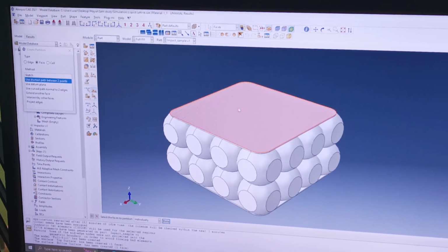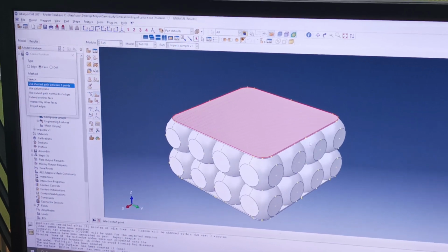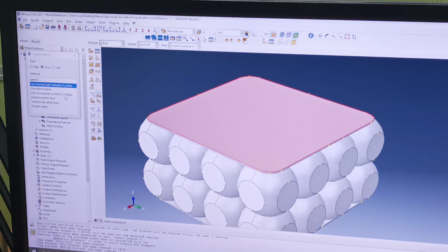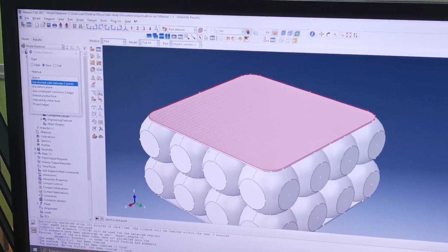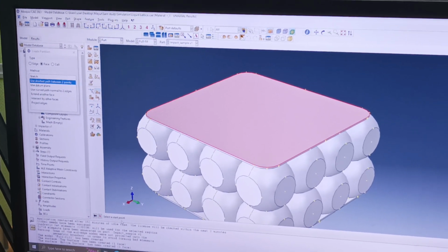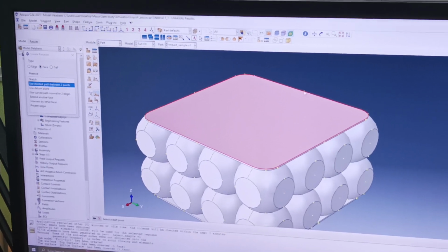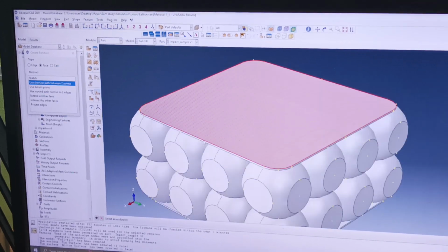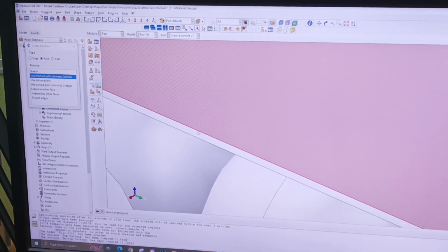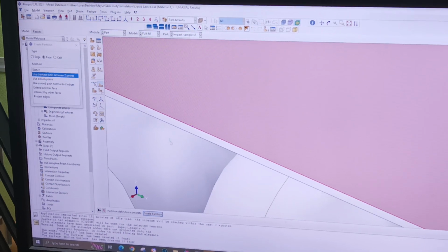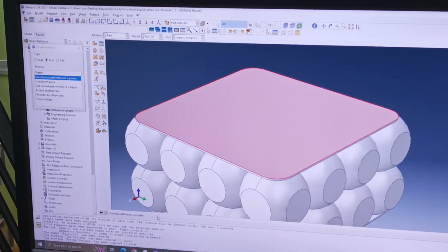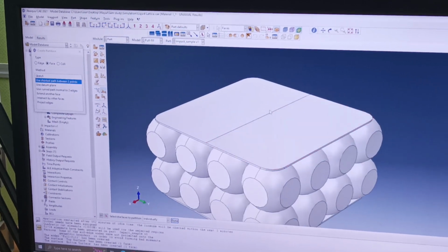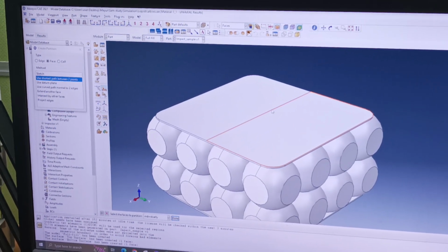Again, select the surface and done. So now you see there are yellow dots everywhere. Use the shortest path between 2 points. We haven't selected the 2 points yet. You see it says select a start point. So let me just select the start point. One is this, because this is the center. One should be here. Click on create partition. It will separate the two surfaces. Now I want the center, so I will just partition these two. Then I can get the center.